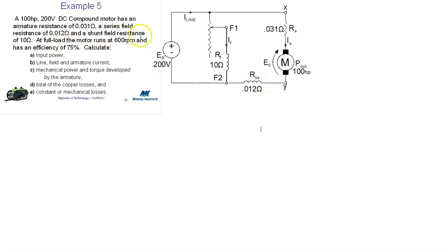And then a shunt field resistance, which is usually a bit bigger because it's in parallel instead of series, 10 ohms. So I've included the rheostat. That's not really necessary, but I usually do. And we got our shunt winding symbol, and 10 ohms represents, remember, that total resistance of that whole shunt circuit. Okay, so there's our numbers.